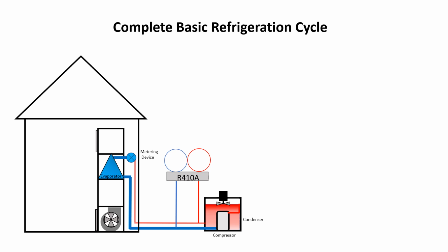We are now ready to go over the entire refrigeration cycle now that we've learned the components, the pipe connections, and how to take pressure and temperature readings so we can calculate superheat and subcooling. Remember that we will immediately convert refrigerant pressure into saturation temperature.